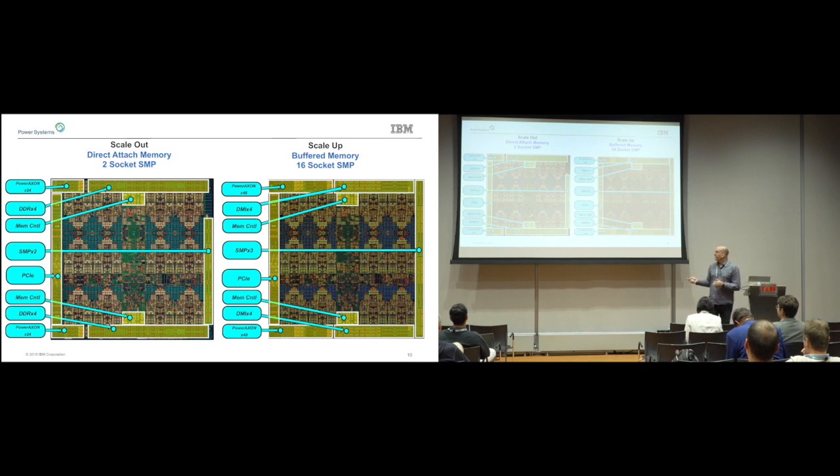This is really highlighting how end-of-the-line DDR PHYs are. They're simply very large. This is the Centaur DMI-based Power 9 chip. This is 4 channels of DMI, right? It's smaller, about half the size of that. So per wire, this is running at 9.6 gig, at 2666.